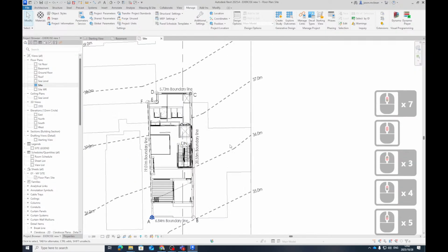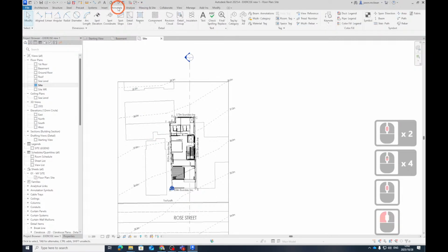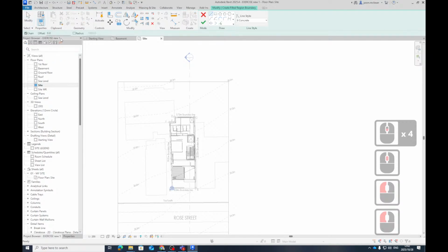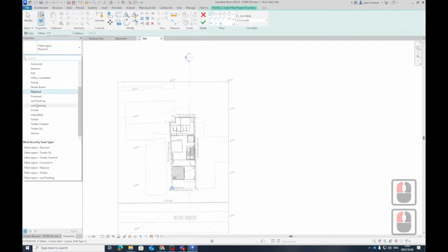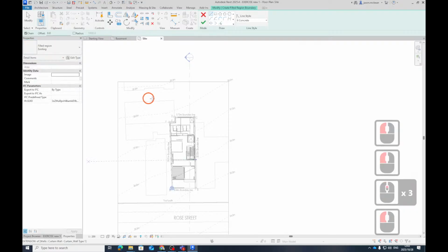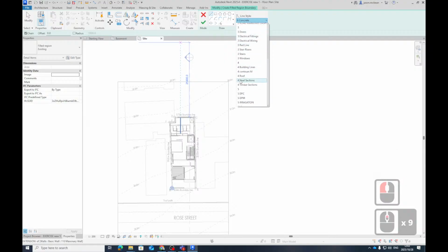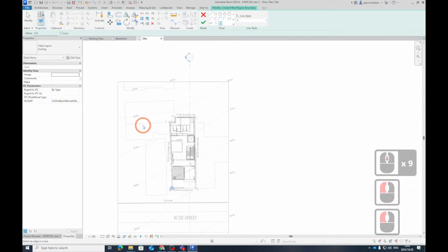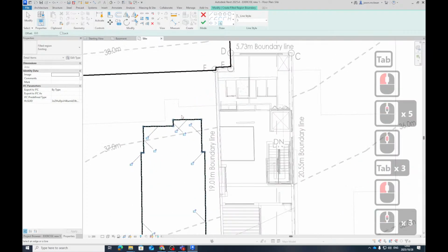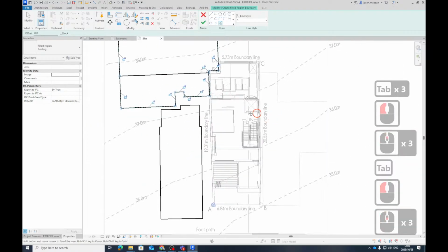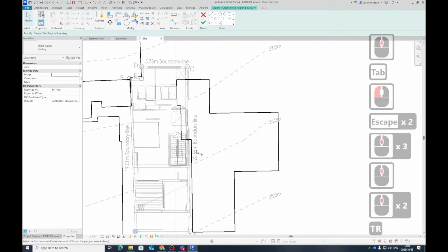Technically, it's very easy. You're going to go to architecture, you're drafting, annotate, region. Guess what? If you go to fold region, you're going to say existing. There's existing here. These lines are usually quite thick, line weight 3 or 4, maybe 5. Watch this. Tab, tab, bang. Quick, eh? Tab, tab, bang. Now when they are connected, I'll explain why. We'll fix that in a minute. Okay, now, when this happens, trim.